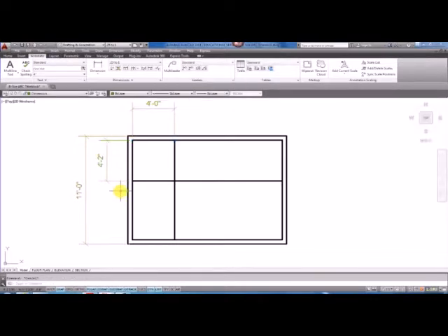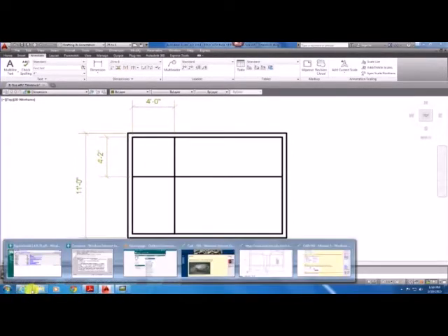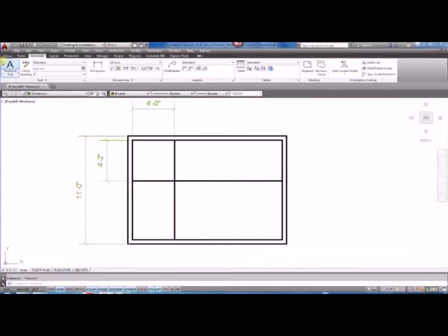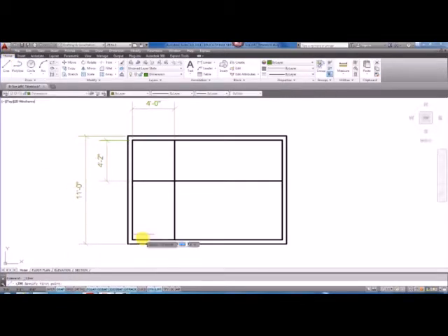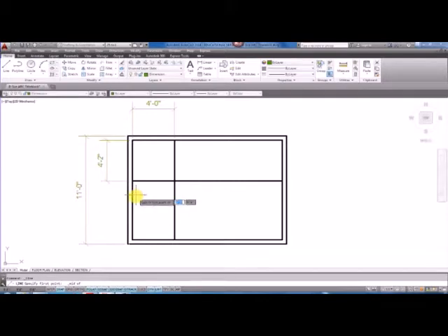Okay, now the way the drawing looks, we need to kind of do a little bit of calculating, and what I found is the middle of the stair tread is in the middle of the wall, and so what we'll do is we'll come back here and we'll make a line from the midpoint. And to get a midpoint O-snap, you can hold the shift key and right mouse click and select midpoint.